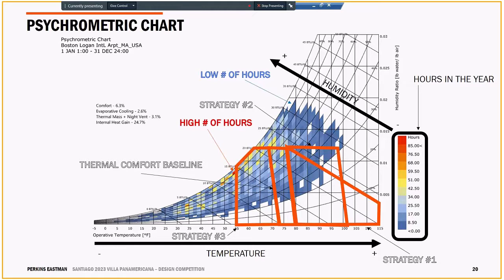So in this particular climate, insulating your envelope and creating it airtight can have a big impact on the amount of heat that you need to supplement a building with. And again, what this chart is telling us and is proving our theory that Boston is pretty much a predominantly cold city in which passive heating design strategies are going to have a bigger impact in terms of thermal comfort than passive cooling strategies. Now, we don't have this data now, but if we were to look at the 2080 climate file for Boston and the temperatures are rising, you would see that passive cooling strategies start to become a little bit more important and a little bit more valuable. So that might be something that would be considered.